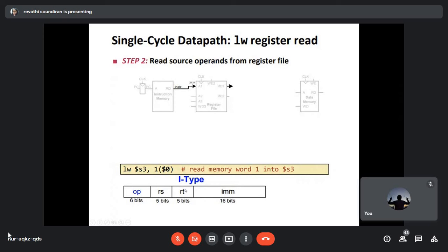Then you have your target register, then your source register. The 5 bits from 21 to 25 are dedicated to the source register. It is going to decode this source register and find the address in the register file. Those 5 bits are passed here to the address.